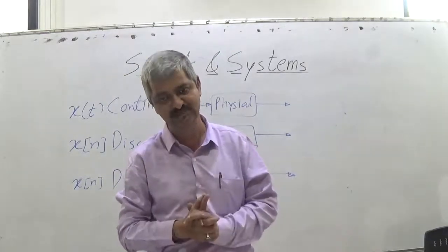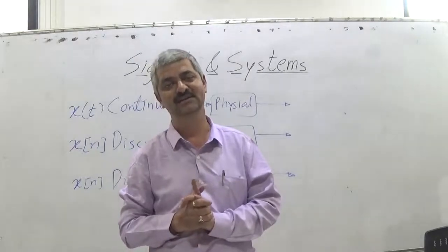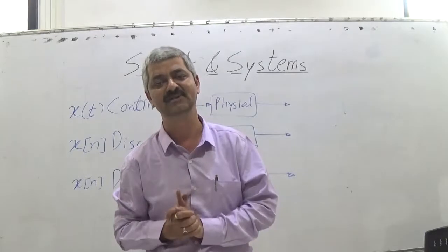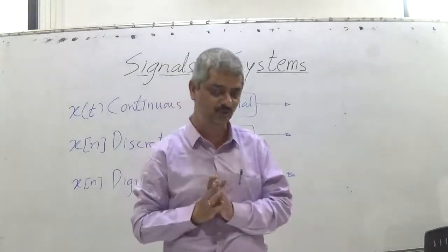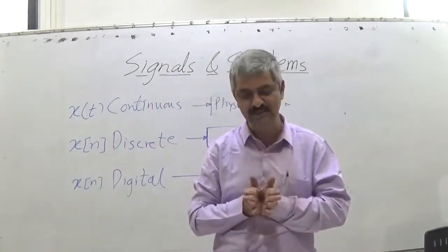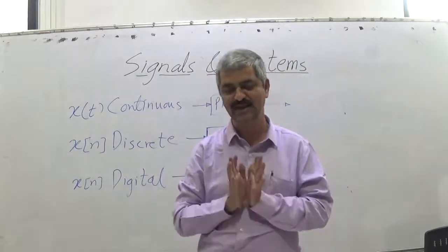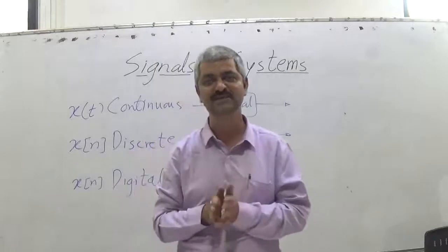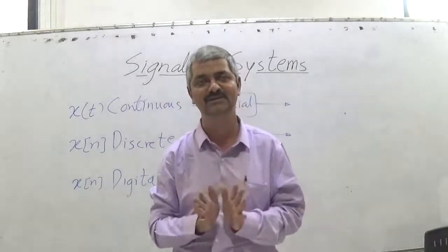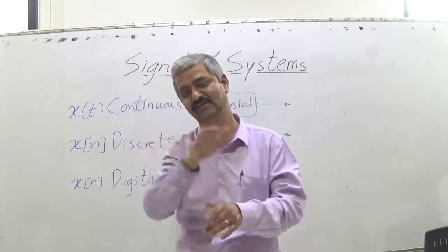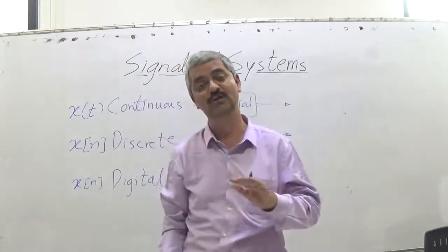So first is meter, next is decimeter, next is centimeter, next is millimeter. You are having a millimeter resolution. So in 4 digits you are expressing using millimeter resolution, then the maximum length you can express is around 10 meters, 9.999 meters. If there is a 20 meter length, then this scale is of no use. You will not be able to express it.